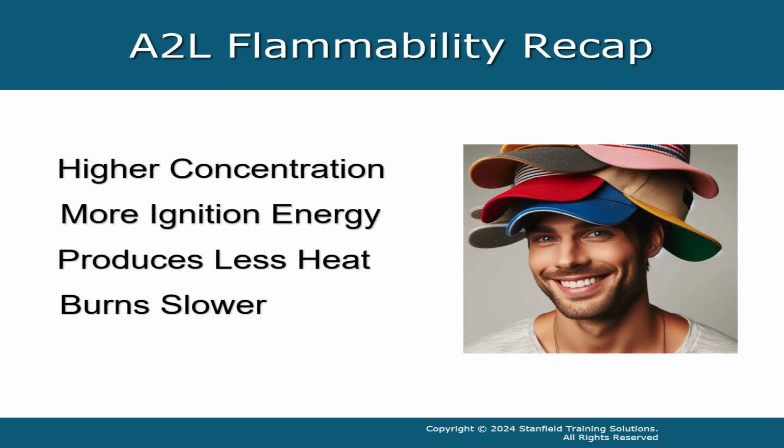Let's recap what we've learned about A2L refrigerant. It takes a higher concentration of refrigerant to form a flammable mixture. It takes more ignition energy to ignite that mixture. It produces less heat if it does burn, and it burns far slower when it burns. As a result, A2L refrigerant will not sustain its own combustion.